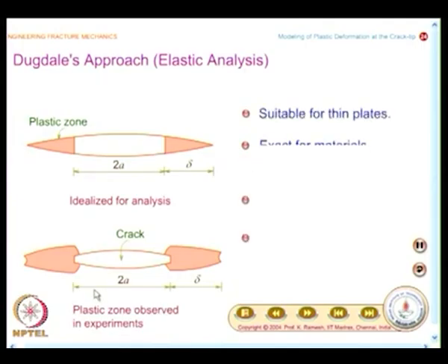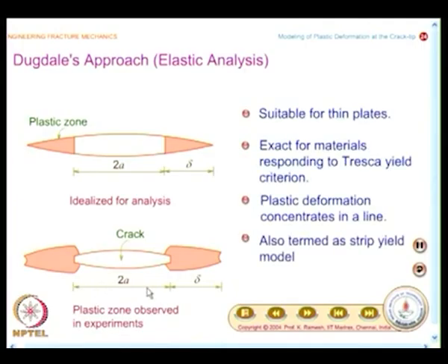So, what you find here is you have a crack of length 2a, there is an extent of plastic zone which is depicted as delta, and we would also see the experimental result and reconvince ourselves that this kind of picturization is what is seen in the actual experimentation. A figure like this is taken up for mathematical analysis,